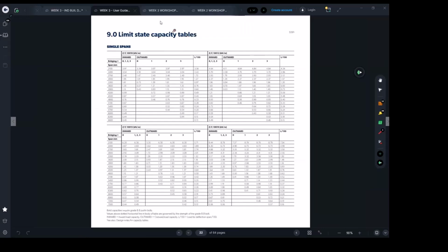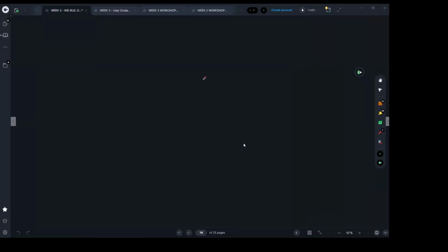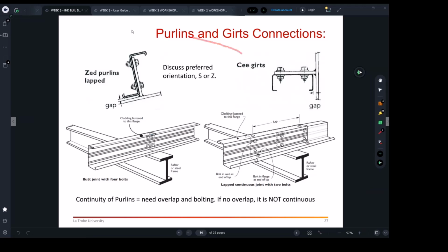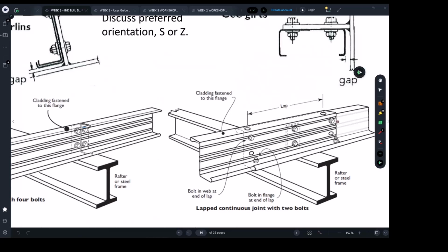All right, so if I go back to my lecture notes, just to continue, as I said, these diagrams are very helpful. They help the contractors to determine how much lap, now up to us to decide whether it's 0.5 meter or there is a particular size of lap. As I said, we lap above the support, which is the roof rafter here. We lap, that will help the section take more bending and flexion. By section, I'm talking about this section, the purlin or girt itself.